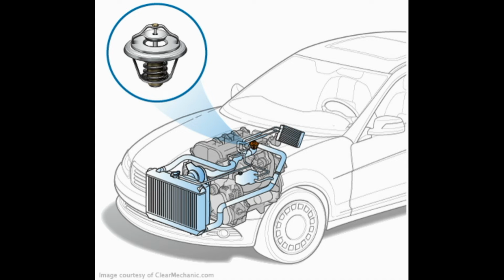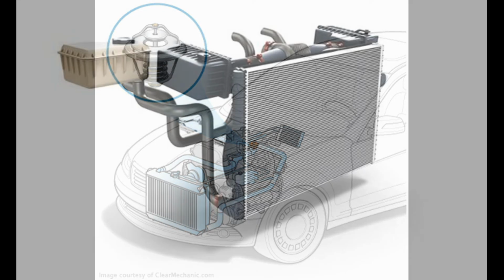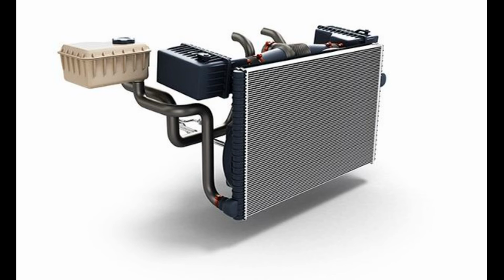5. Rubber hoses. In the engine cooling system, these rubber hoses are required to make connections between the water pump, radiator and engine so that water or coolant will flow through them, thus completing the circuit. 6. Radiator overflow tank. It is a plastic tank generally mounted close to the radiator and has an inlet port connected with the radiator and one overflow outlet. It is the same tank where you put in water before a ride.